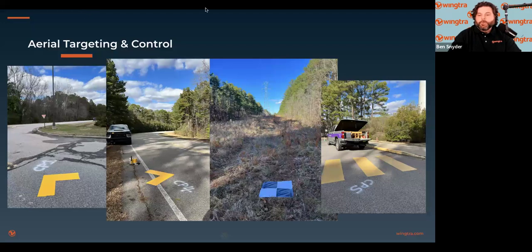Great. We have another question asking about the ability to fly the LiDAR in the Wingtra One Gen 2 at night. Can answer this one just really quickly. Certainly, the LiDAR data is not dependent upon light to collect, and you could. The big thing here is, wherever you're located in the world, it depends upon what the regulations say and what your regulatory body says about flying at night, so obviously keep that in mind.